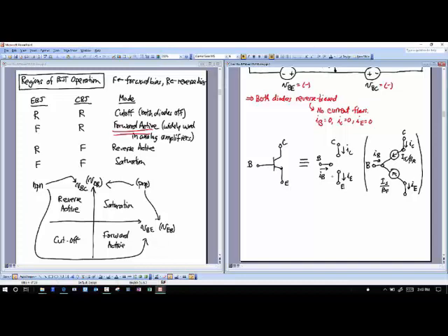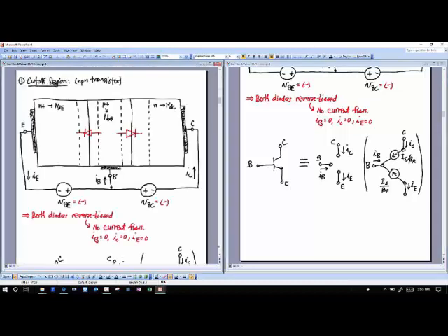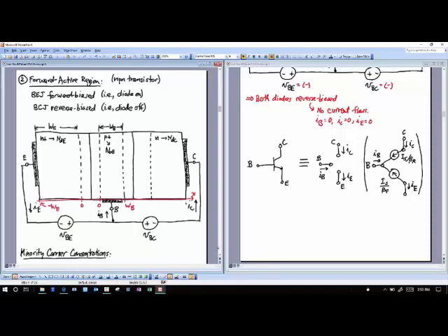If I wanted to be really accurate, if I wanted a bad grade in this class, I could use this model here, which models the saturation currents for reverse biased diodes. There are going to be tiny little currents, femtoamps or less. If you spend all your time worrying about those femtoamps, you will get a bad grade in this class. I'll just be blunt. You need to be able to approximate this away. So that's a model for cutoff right there.